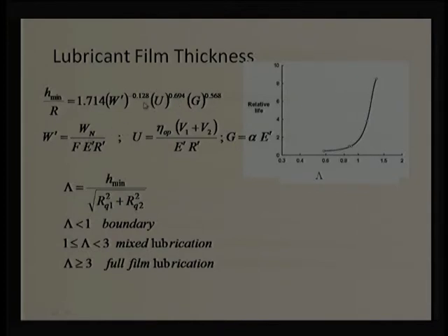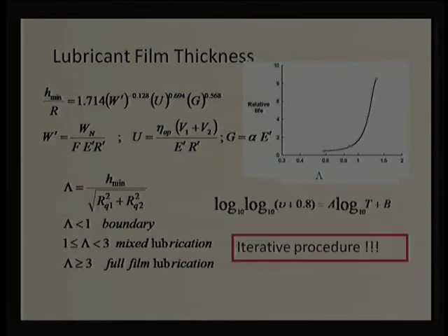So, there is a significant difference, about 5 times, in the power itself. We need to see what is more suitable, increasing the speed or decreasing the load, and go ahead with whichever is more beneficial. But again a trade-off will come whenever we increase the velocity. Naturally, there will be more churning losses, and when there are more churning losses, there is a power loss. So, we need some trade-off in that.